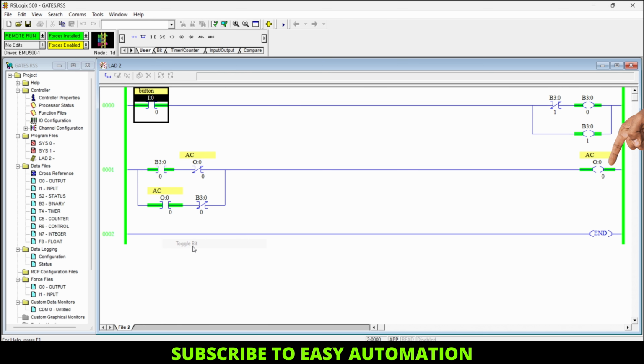But as our output is on, this NC contact has become NO, so that trigger pulse will go low here only and will not pass through this NO contact. But that trigger pulse then comes to this NC contact, which will turn this NC contact NO, by which our supply will break here and our output will go off. So this was the idea behind the off condition.